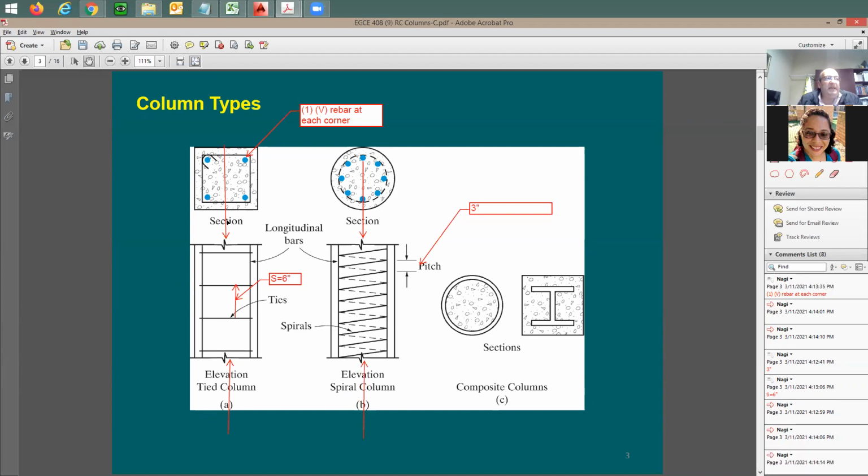Now, when you put axial load, the column wants to open up. Because when you have this high axial force coming to it, it wants to open up, and what's going to keep it in place is going to be these ties. So this axial load is going to be causing lateral strains, and these lateral strains want to open the concrete up.